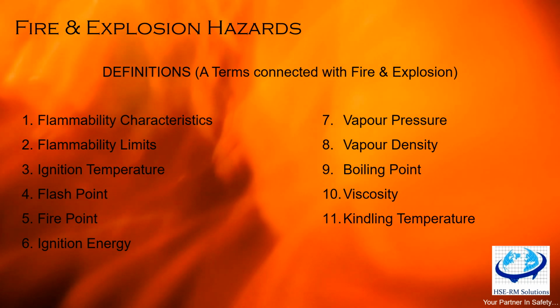In a tank, a viscous liquid layer containing a small quantity of water, by heat conduction, boils to form steam, expanding to 1700 times the water volume. This causes boil over of the liquid, forcing the liquid out under violent force. In the case of large tanks, the burning oil can cover a wide area.